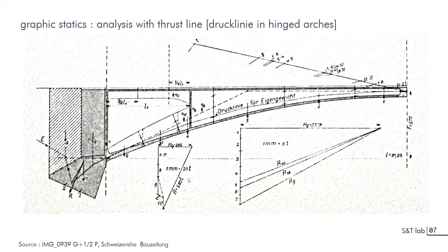And you see all the typical elements of the characteristic analysis in graphic statics. You will see also that the utility is to make measures from some reference to get the difference of position between the thrust line and the line that gathers the level of the center of gravity. That will deliver directly the bending forces, and we will be analyzing this in the next slide. This enables you also to make the calculation of the reaction force, its direction, and the composition of the self-weight of the support foundation.